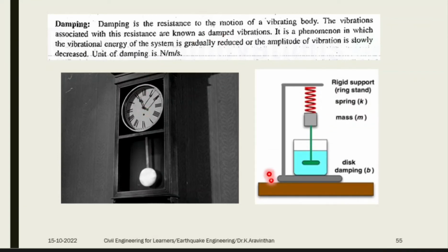Imagine that you have the same kind of vibration here. You have a mass and a spring is attached. Now this is attached to water. You vibrate the object. What will happen? Due to this water, the vibration duration will get reduced. Now you remove this water jar and try the experiment, and it oscillates for a longer duration. If you introduce the water, the vibration is going to get reduced. So if it lasts 3 seconds with the vessel, if you remove the vessel, it will last 30 seconds. So what has changed is the damping. If you increase the damping, your system will not vibrate.